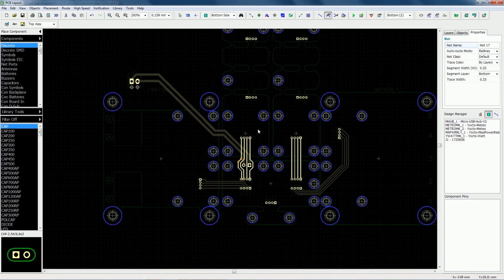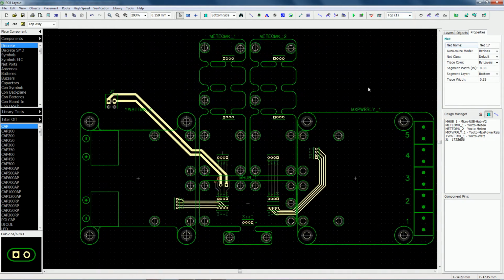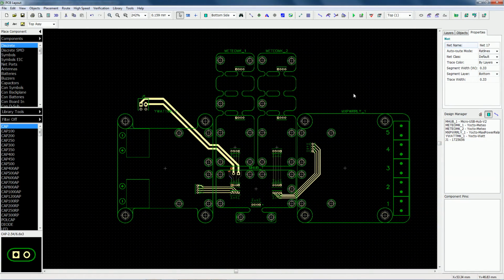Now we are ready to turn back to the top face, have a look at our PCB, and now we'll check that there is no short circuit and that we have routed all lines. So there are 2 check functions: design rules and connected nets. This will tell us in case the PCB doesn't match the schema or if there is a short somewhere.